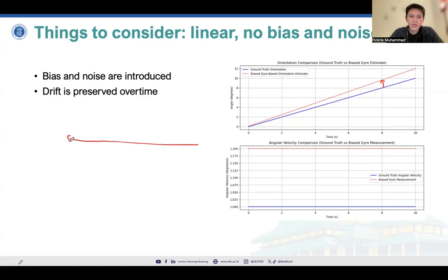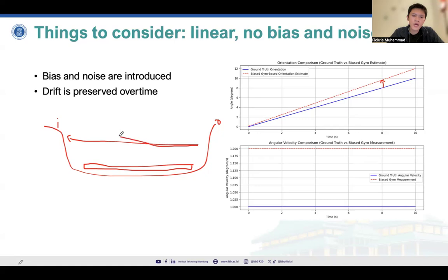So for example, we design the AUV to collect the data from one port to another port. For example, here, this is port 0, this is port 1, port I, and then we set the mission plan to go from one port and then collect or detect the underwater pipe, for example. Here, it sees the underwater pipe, it has to follow the pipe, but because of the drift over time, it might no longer follow the pipe, so it might go that way instead.